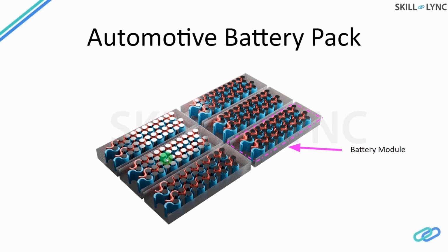For example, say that the BMS detects there are certain cells that are at fault. You don't have to worry about replacing or removing the entire battery pack. You might just replace or remove a single module. And from an operational voltage point of view, automotive battery packs have really high voltage. So if the modules are smaller, the risk of having an operational hazard while operating on a battery module is less because the operational voltage per module is going to be low.